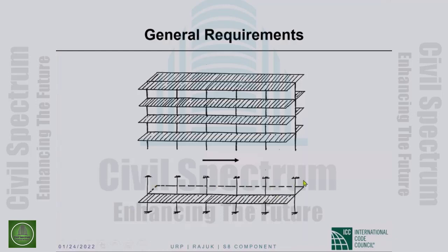So this is our slab strip at a particular level. These are the attached columns. The columns below will be considered fixed at the level below, and the columns above will be considered fixed at the level above. This subsystem will give you sufficiently accurate predictions of bending moment, shear forces, etc. under gravity loads. Okay. So under lateral loads, this is our subsystem. Under lateral load, this is our subsystem. This is the direction of analysis.